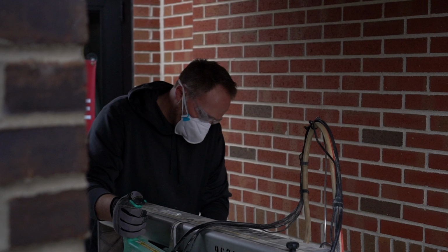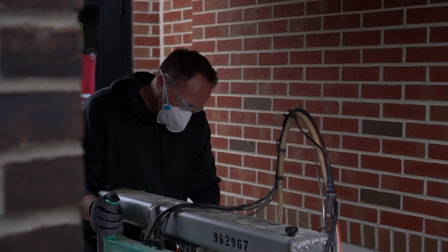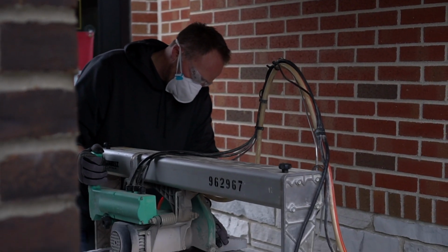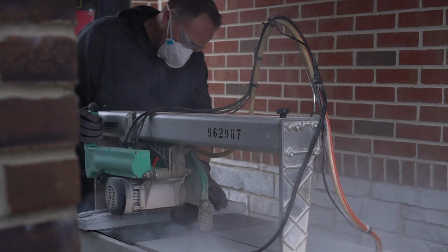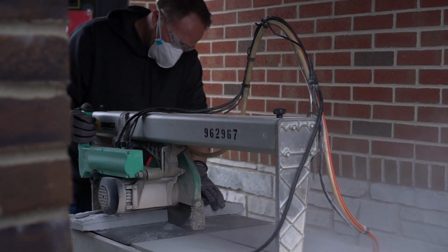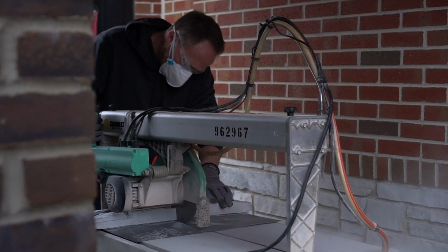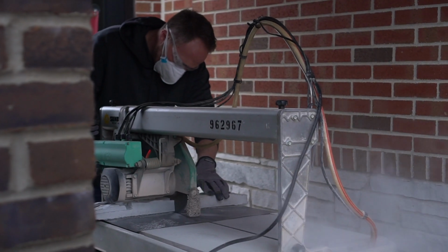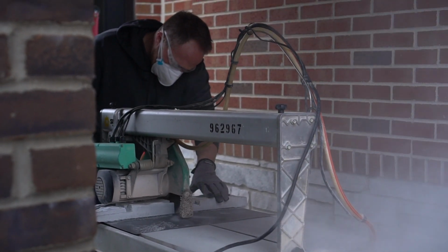Always follow safe tool operation instructions provided by tool manufacturers. Some tools recommend or require a full face shield. Concrete dust can cause skin and eye irritation. To help minimize this risk, wear a long sleeve shirt, long pants, gloves, and safety glasses with side shields when cutting and installing material. Wash hands and face with soap and warm water after working with concrete-based products.